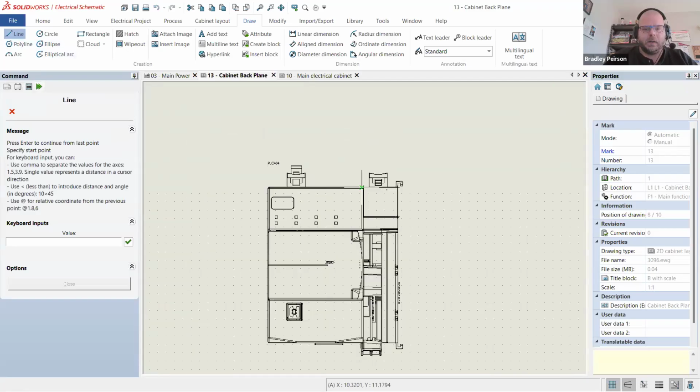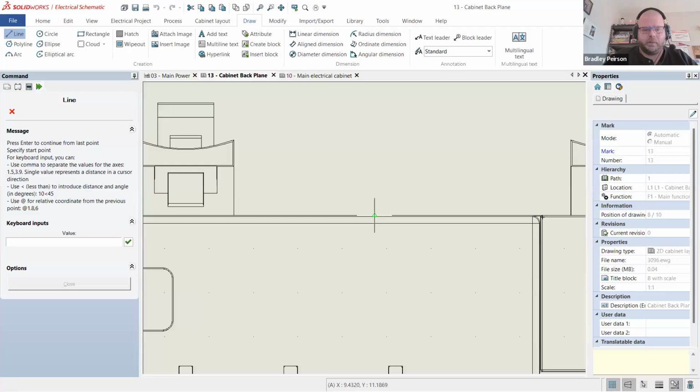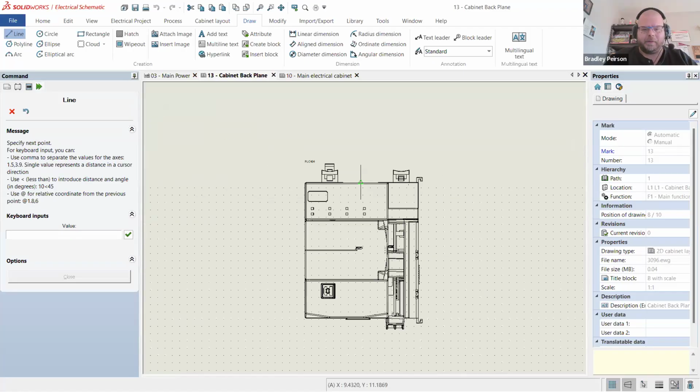So, construction lines are where it's at when it comes to that. It doesn't matter really where I put the construction line, just not on these tabs, because those are out of the scope. But the main body of the PLC, if I remember right, Allen Bradley wants something ridiculous like 6 inches. Now they never get it. Not from me anyway. They might get four if I can spare it. Usually probably three.